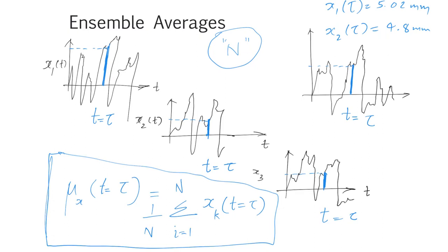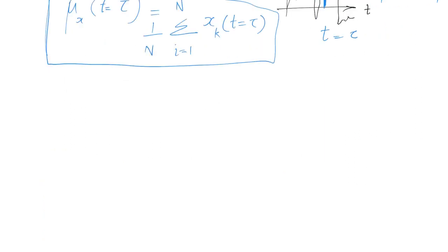Similarly, let's say my x3 of tau was coming around 5.2 mm and x4 of tau was coming around 3 mm. So on an average, we can see 5 seconds into the landing, I am more or less seeing a displacement around 5 mm for my landing gear.